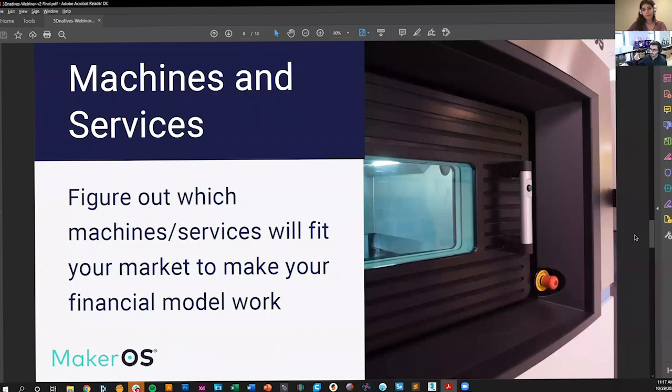So once each machine gets to a certain utilization, machine utilization rate is basically a percentage. So in a given month, how much time is going to be taken up on that machine. My recommendation is, if the machine utilization rate on one of your machines starts approaching 60 to 70%, it might be worthwhile to look at purchasing another machine to help fill in those gaps, but also to offer maybe a different type of capability that you can also use as an upsell.